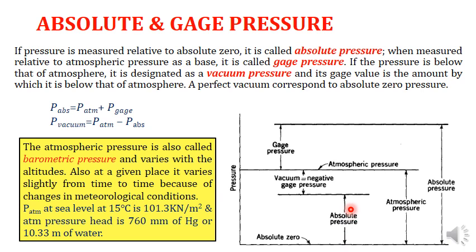That is very important. Whatever measuring device you are using to measure the pressure or the vacuum, you must be clear whether this device uses the absolute pressure or the atmospheric pressure as reference, and then correspondingly consider the negative or the positive sign. In this way, P absolute will be equal to P atmospheric plus P gauge.